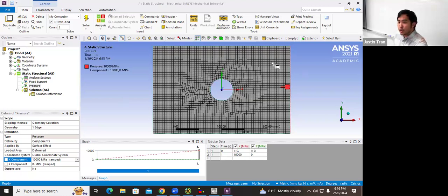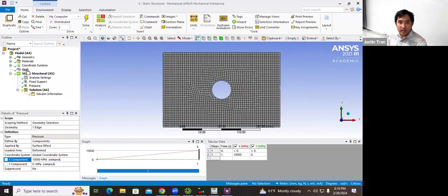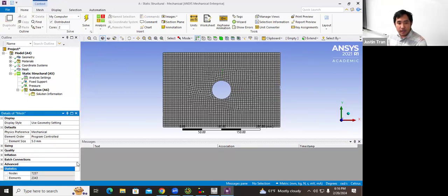Usually at this point, we have our mesh, we have our elements, we have our boundary conditions. If this were a traditional direct stiffness type problem or a hand calculation, we would start assembling our element stiffness matrices. The problem here is that each of these tiny little elements is going to have its own element stiffness matrix. So for a mesh of 2,300 elements, you would have to write 2,300 element stiffness matrices, which is only something a cruel and unusual person would make you do.